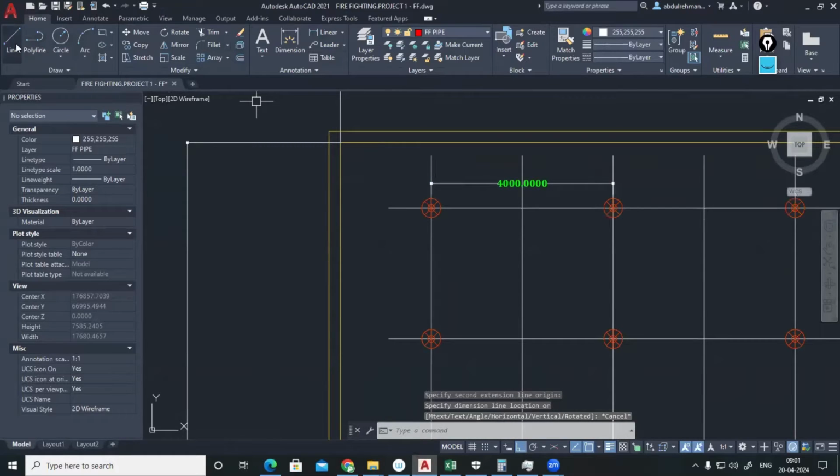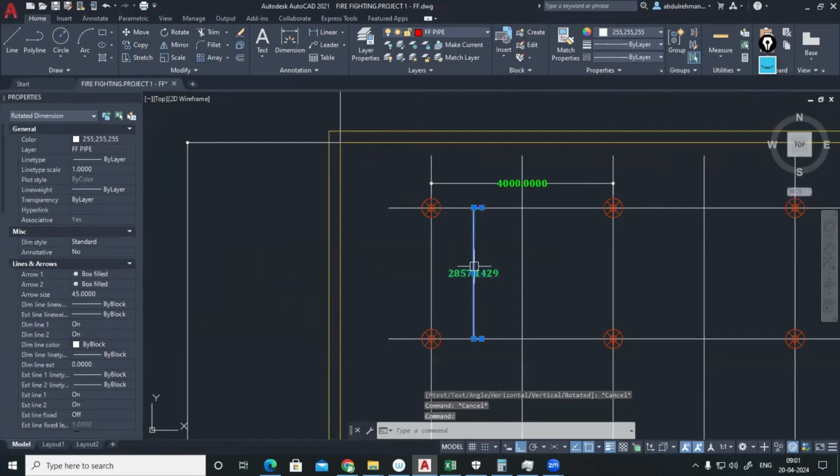So the distance between this 2 sprinkler, now it has changed a little bit when we are adjusting that into 7 number of sprinkler, 2.857. So distance from the wall will be 2.857 divided by 2. Like that only it will come 1.428. Okay. Fine.